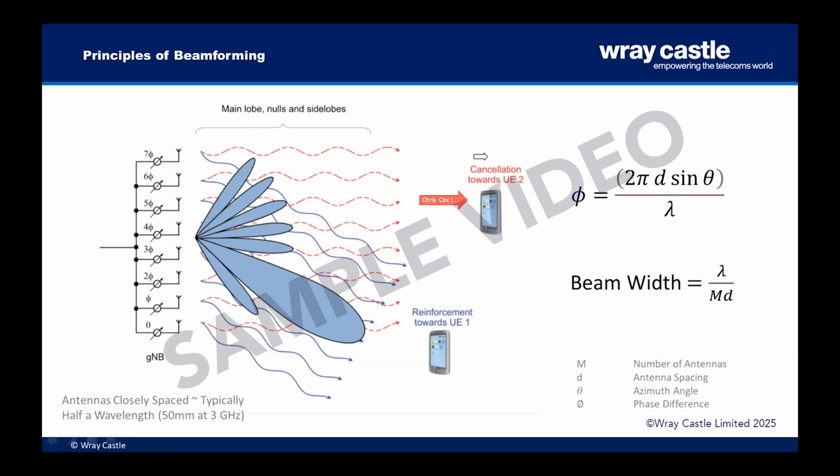And indeed, viewed from this precise direction, the radio wave at the top will cancel out completely with the next but one wave down. And this radio wave will cancel out with this one. All the radio waves will mutually cancel out, and mobile number two will receive nothing at all. At intermediate directions, there might be partial reinforcement and partial cancellation.